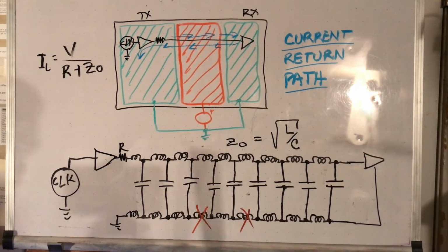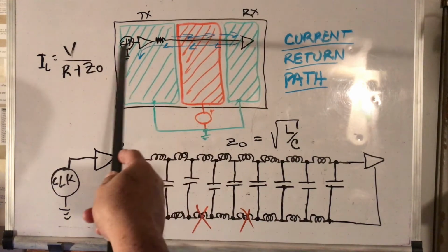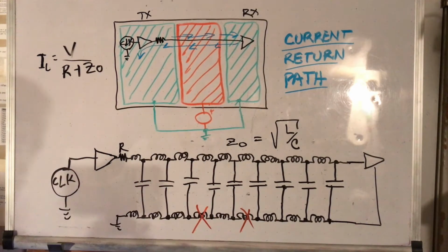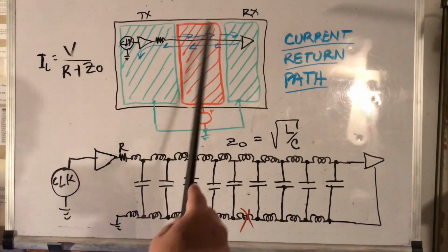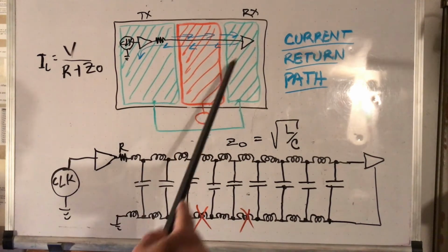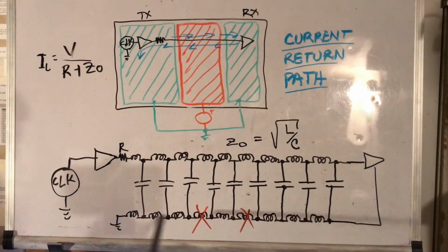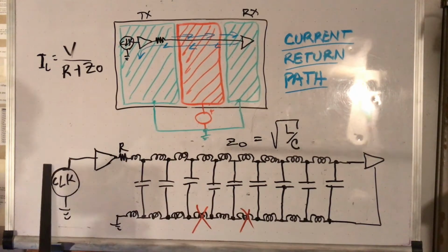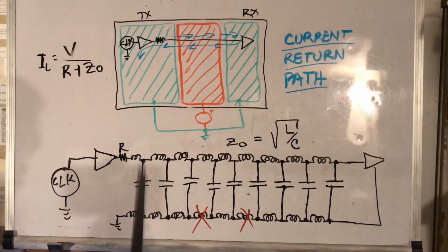And so you have to find a way to keep this current returning properly, following the line, in the path of least inductance, because the power plane is not perfect. It may have a very low inductance, but it still has inductance, and on top of that you go and cut it, so you essentially increase the inductance tremendously, and there is no way to properly return. So that is the statement of the problem. Hang on, and we'll see the demonstration.